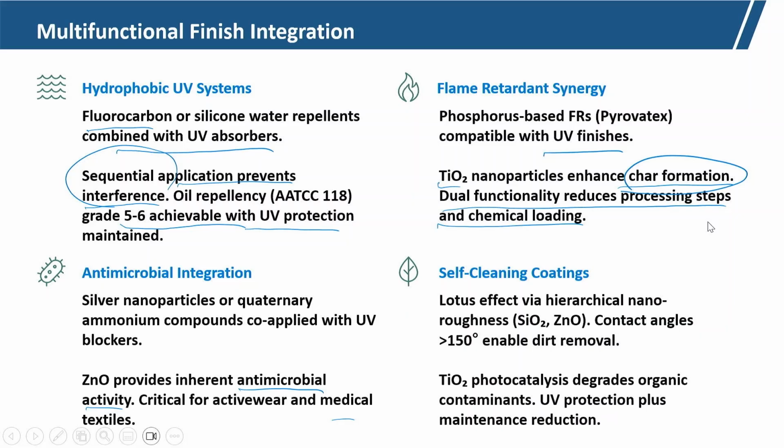Self cleaning coating, like the lotus effect via hierarchical nano roughness, we can achieve using silicon dioxide and or zinc oxide, where we can achieve a contact angle of more than 150 degrees.